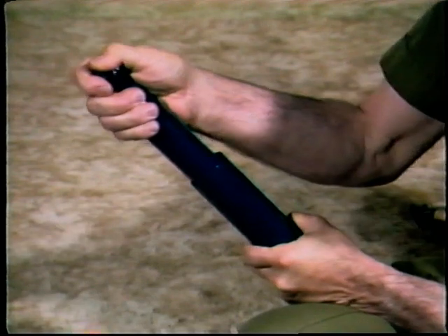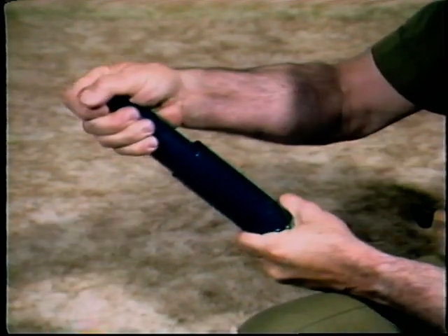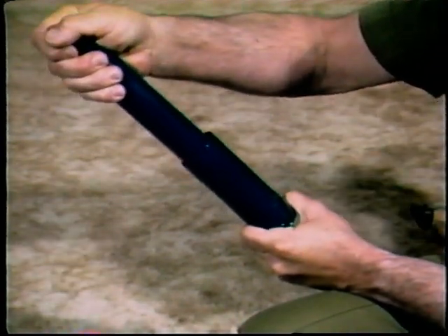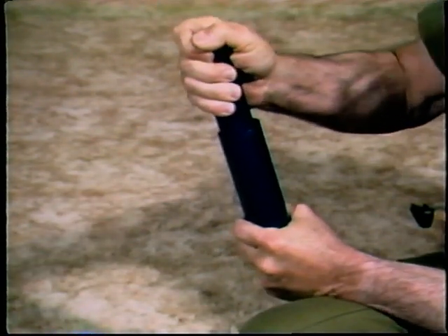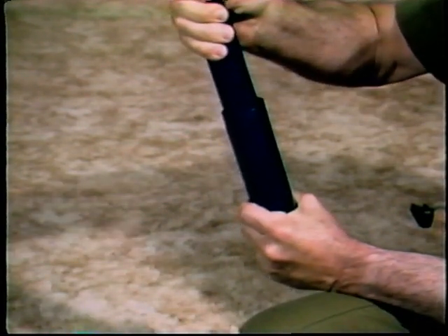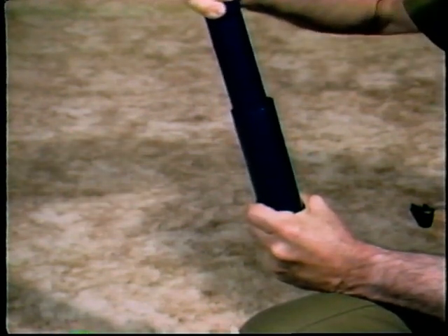But if the force on the actuator varies during the stroke, or if extremely stable velocity control is necessary, the use of a hydraulic dash pot may be required. A shock absorber on your automobile is a type of dash pot. And just as it smooths out the bumps in the road, a dash pot in a pneumatic circuit can smooth out the irregularities in a cylinder's motion.